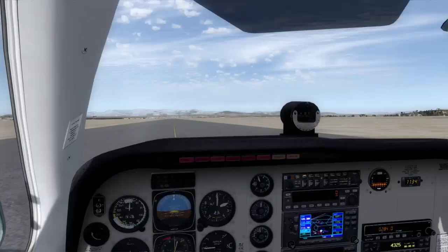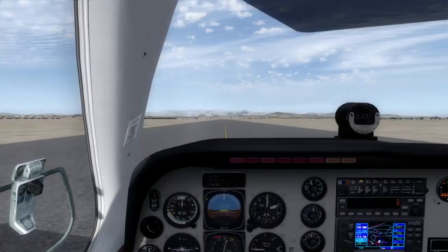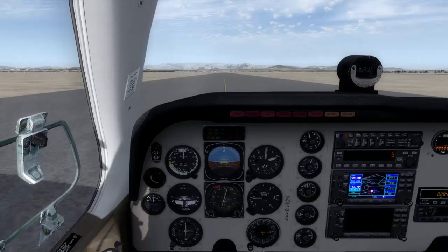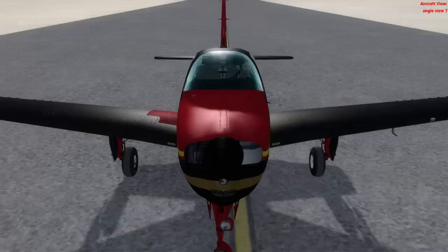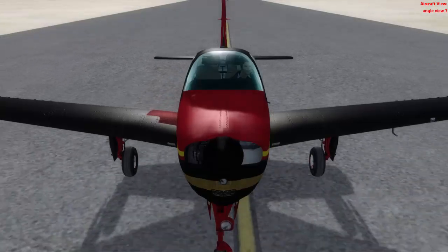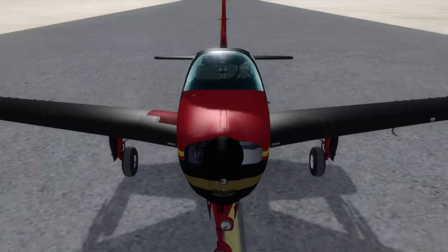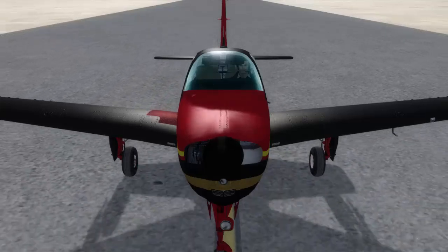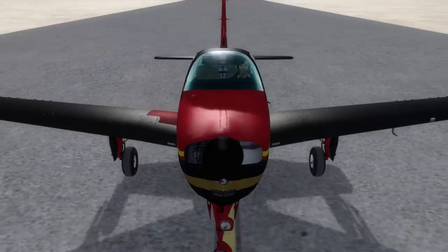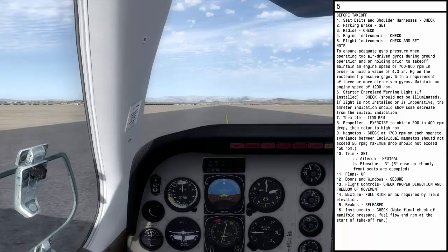Okay, so we continue with the taxi to the runway to take off, and also we will have a lot of time to take a look at the departure procedure. We will follow the standard instrumental departure chart, then we will connect with the enroute chart. Then we will connect also with the STAR chart, which is the arrival chart, and finally we will use the instrumental approach chart, IAC chart, to follow the proper descent rate, to follow the proper radial, and to tackle a VOR DME approach as we should.